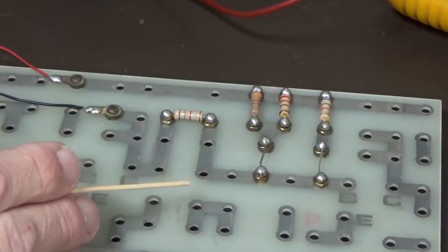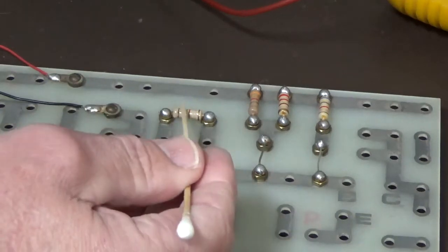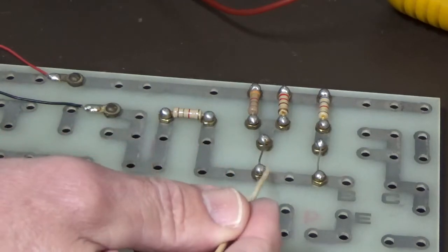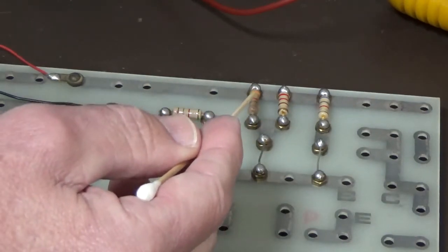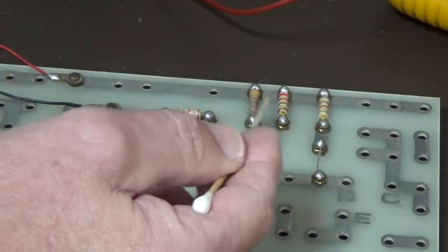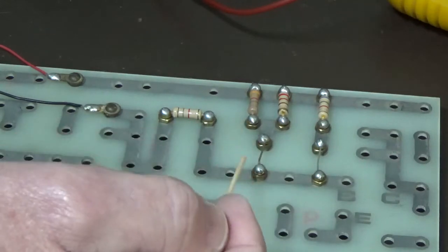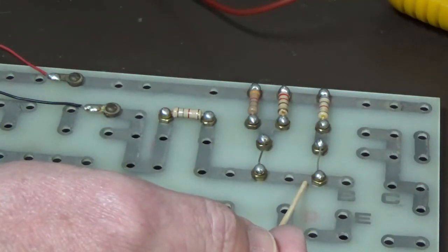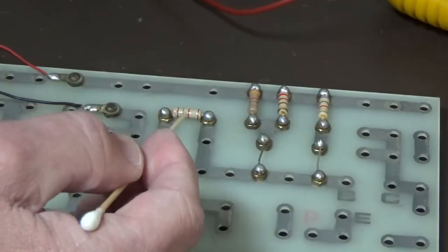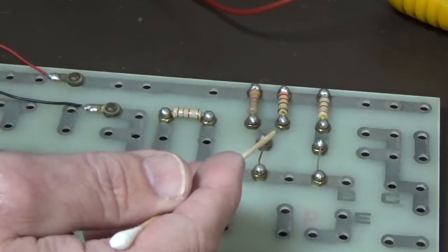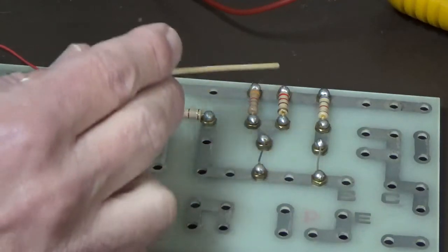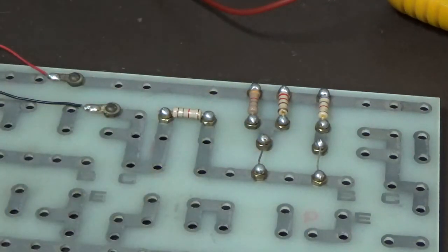This is the second circuit that we had up on the board. You've got a 1.5k in the negative rail, and then we had our 3.3k, 220 ohm, and then 6.8k, and these are in parallel. As you can see here, they're all coming off the negative side and they're all attached to the positive side. So what we'll do now is measure the total resistance and see if that comes up close to what we calculated, and then measure the parallel resistance and see if that comes up close to what we calculated.